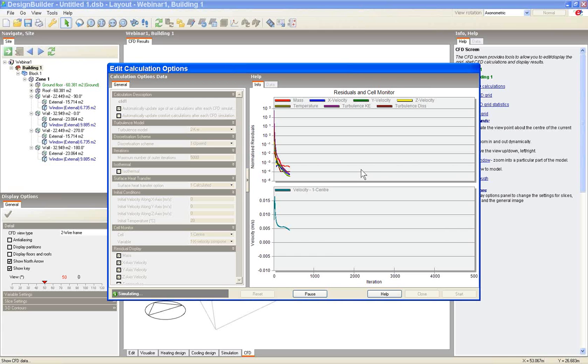That tends to mean either that the boundary conditions are incorrect or the grid is incorrect. So one thing to be careful of is when taking in your boundary conditions. Hopefully they won't be that far out, because you've taken them from EnergyPlus. The issue will then be, is the grid realistic, and is it a uniform grid? Is it a grid that's allowing the simulation to come to a sensible solution?